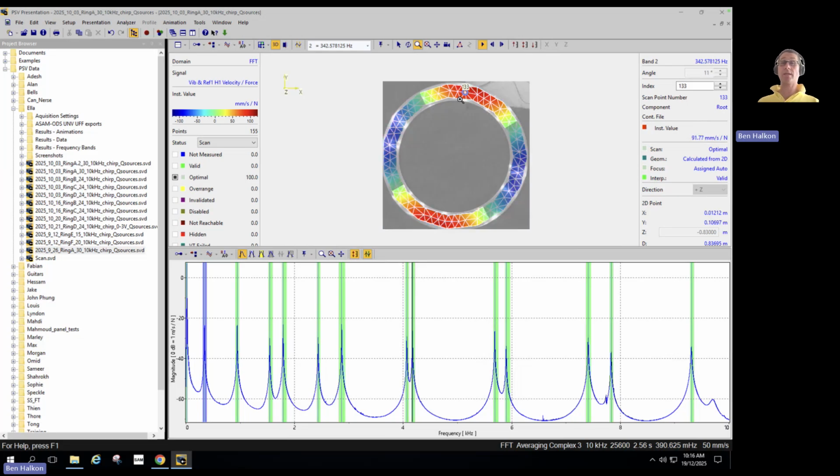It's connected to the back side of the ring, and therefore we have unimpeded access to the top surface with the scanning vibrometer. It's sitting on a piece of foam with a corner cut out here that allows us to position the shaker. And perhaps it's even nearer here at point 18. We need to work that out.